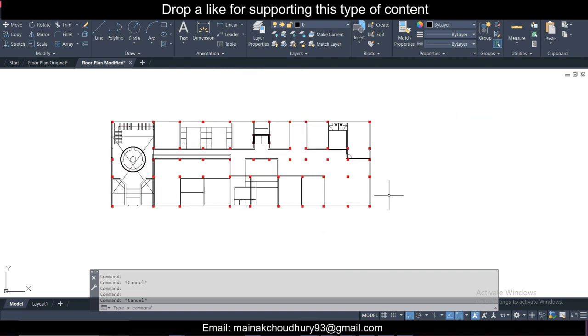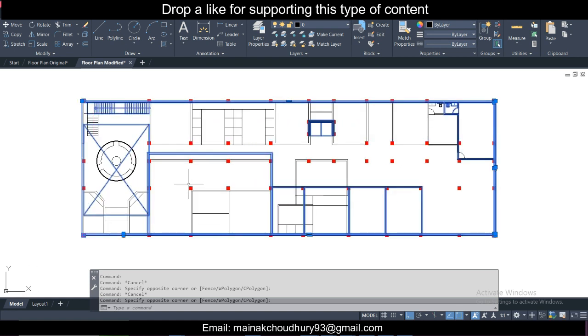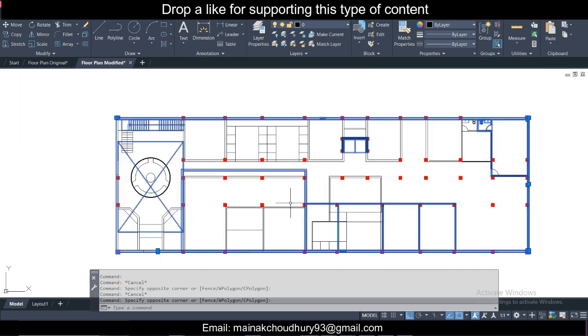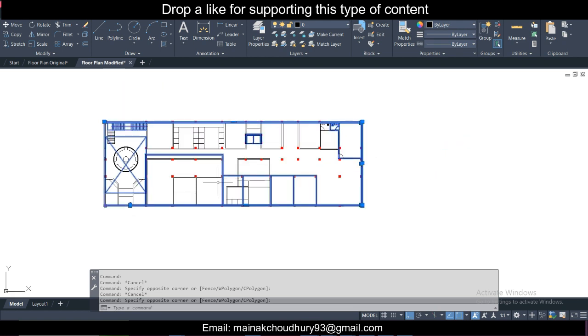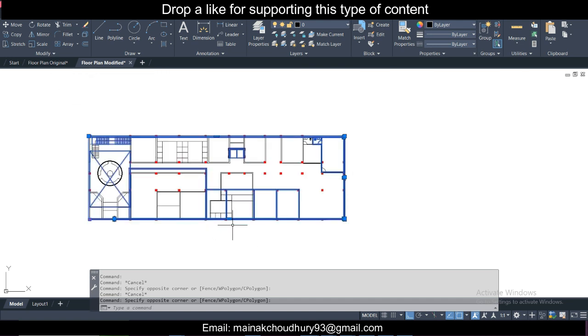So this is actually the first floor, the marked blue one, and the remaining portion is the ground floor. As you can see, I told the architect to adjust this first floor dimension in this line. The remaining is good. Then we check the overlapping, to see whether all the beams and columns are in the correct direction, and whether any column is obstructing any passage. We need to check this. This is a very long process, that's why I didn't make a video of it. With experience you should be able to do that.